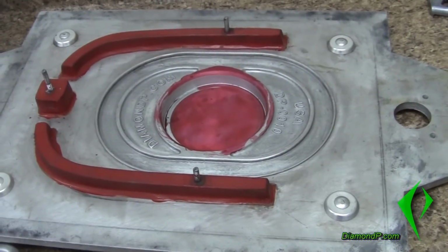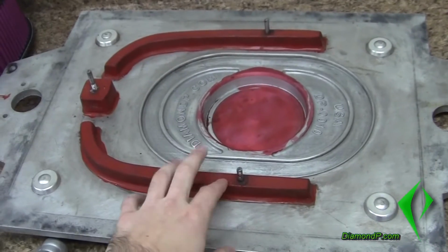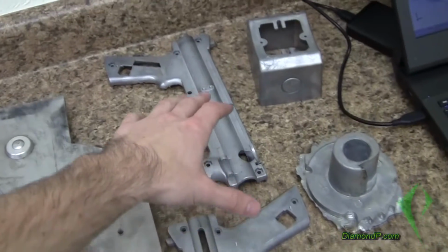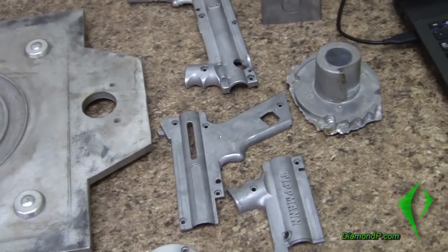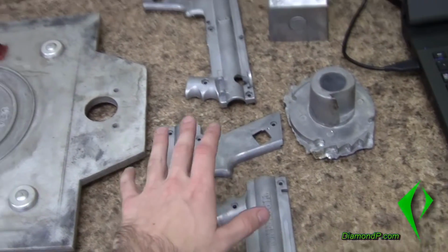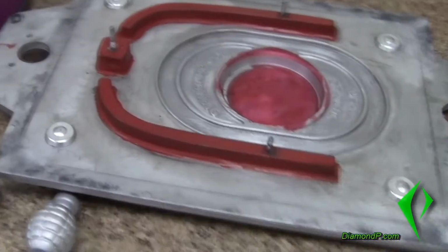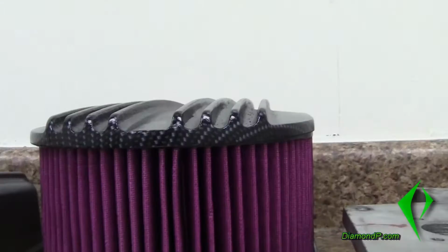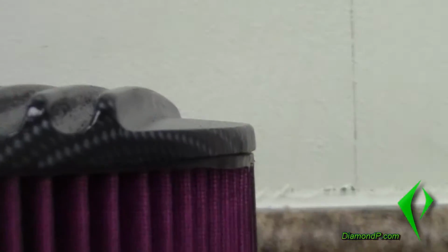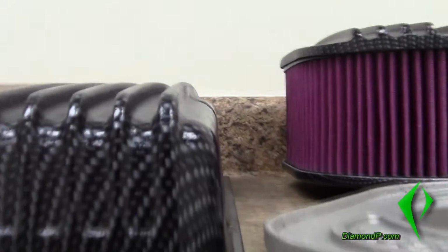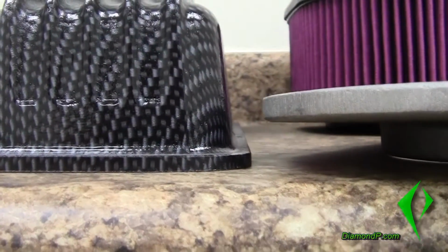And there are different types of castings. This is green sand. You can also do air set or investment castings. These parts over here are die castings, which use steel for the mold instead of sand. It's a lot faster and you can make a lot more parts with this, but the molds are more expensive to make. All these parts have parting lines and draft, and you can see that everything has a slight angle to it. By being able to see the angle, you can tell where the parting line is for the part.